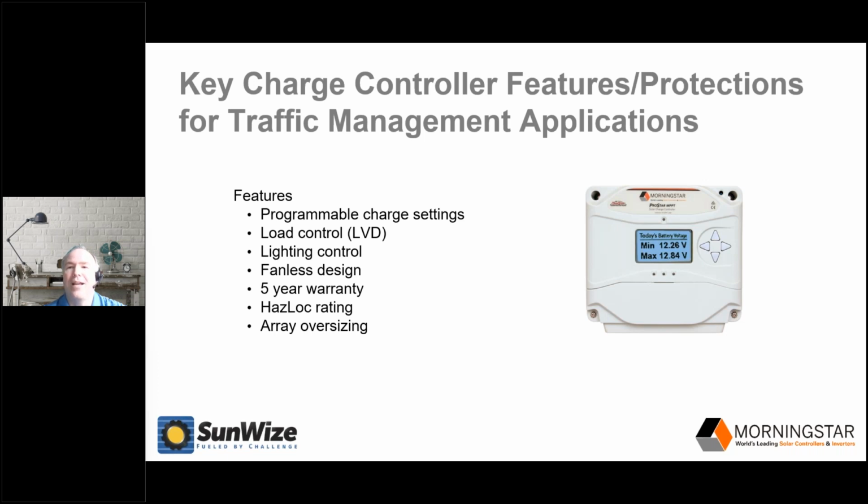Charge controllers in traffic systems have to be reliable and able to withstand transport and all types of weather conditions. So they should have a 5-year warranty and a strong track record for life expectancy well beyond that 5-year warranty. Some traffic management applications associated with chemical spills and gas leaks may warrant controllers with hazardous location ratings, so you can check data sheets for those specifications.